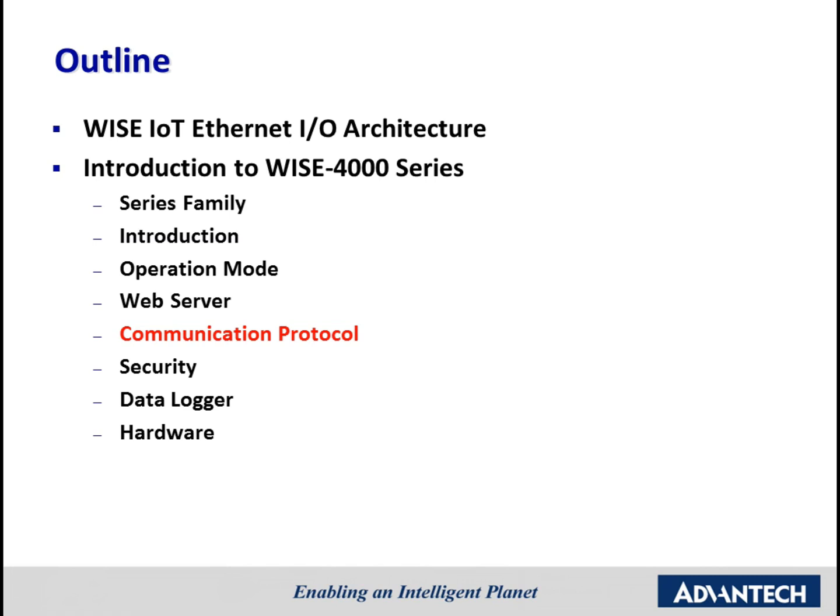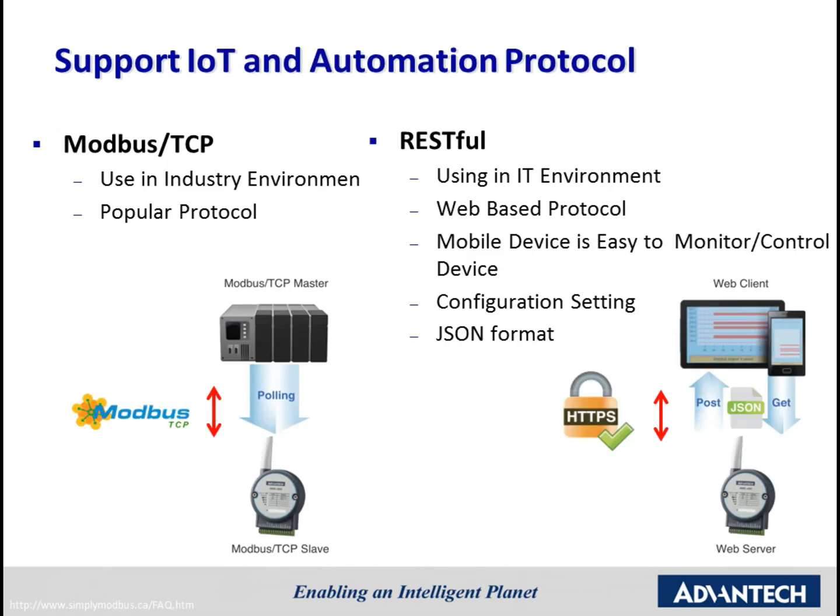Next chapter, let me introduce the communication protocol. WISE supports 3 different kinds of protocol: Modbus TCP, RESTful API, and MQTT protocol. Modbus TCP is widely used in the traditional industry environment. Many controllers support this protocol. Therefore, WISE is very easy to integrate with existing devices.